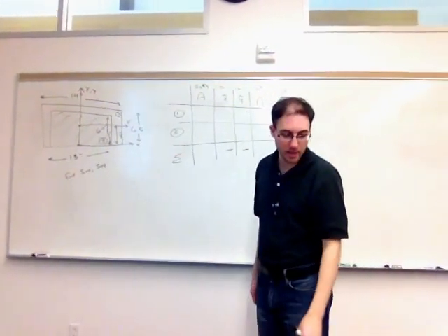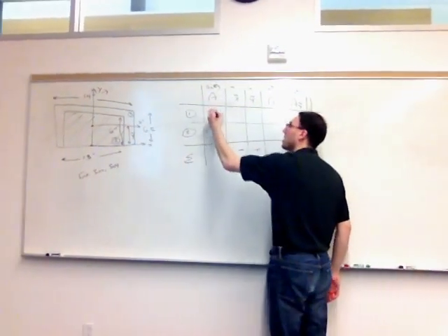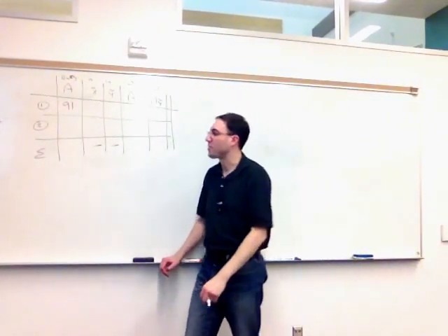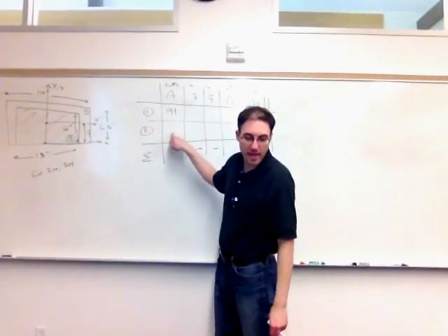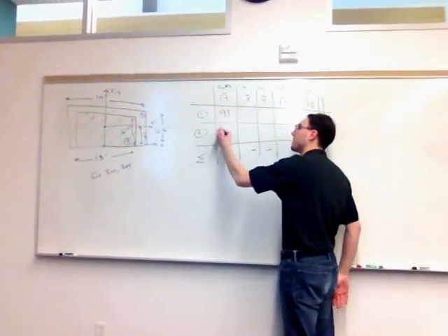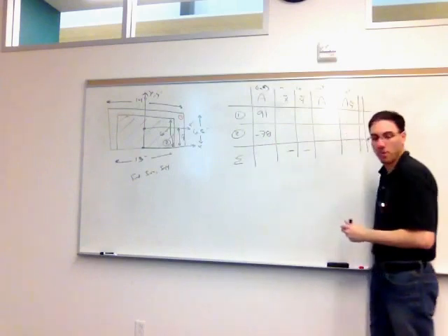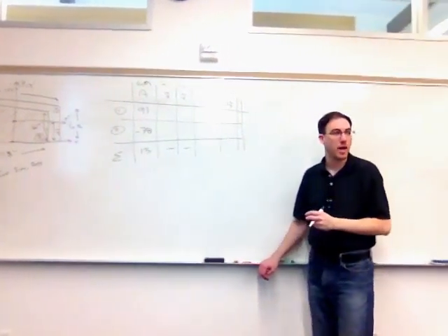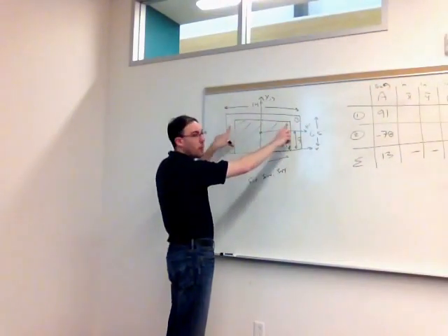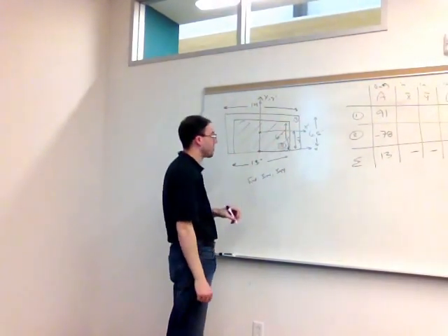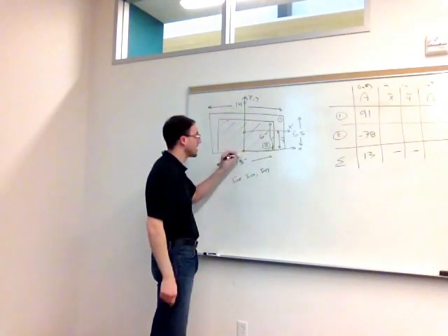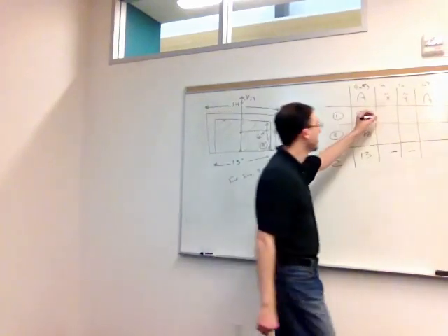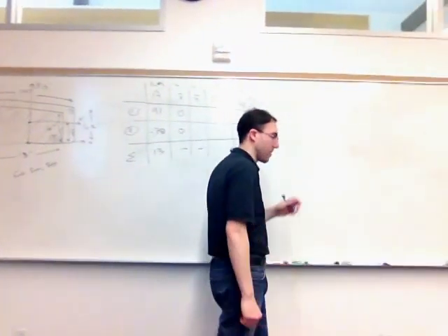6.5 times 14, I'm going to get a positive 91 square inches. Shape 2 is 13 by 6, and it's being cut out, so that's a negative 78. So the total cross-sectional area is only 13 square inches for this channel-shaped beam. Both of them are symmetric around the y-axis, so if I look at the center of my outer shape, it's located on the y-axis, and of my inner shape, also located on the y-axis. Therefore, the x tildes for both shapes are 0.